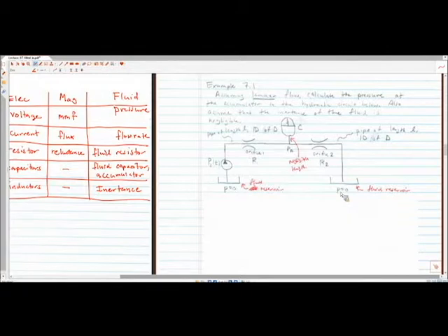All right, so this is asking just calculate the pressure at the accumulator in the hydraulic circuit below. Assume that the inertance of the fluid is negligible. Sometimes the inertance of fluids will be negligible, sometimes it won't. It'll be basically based on how large the system is. If the system is containing a lot of volume, it's going to have an appreciable inertance to it. If it doesn't have a lot of volume, it will not.